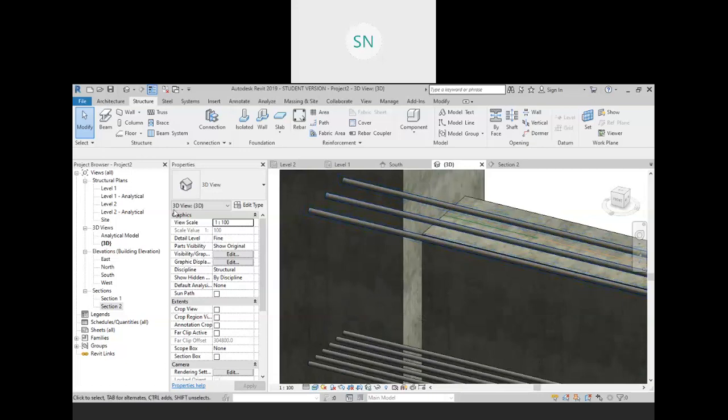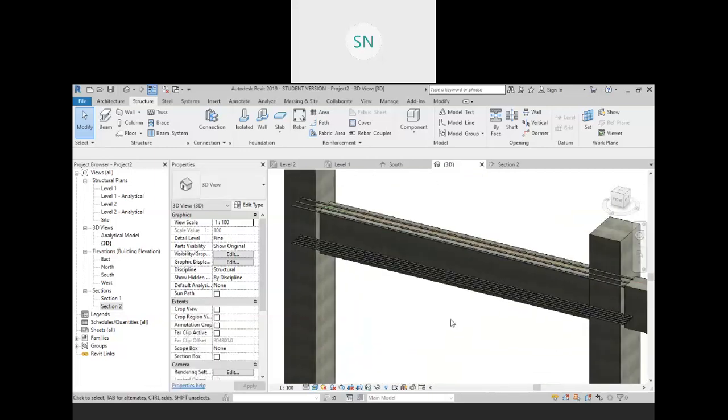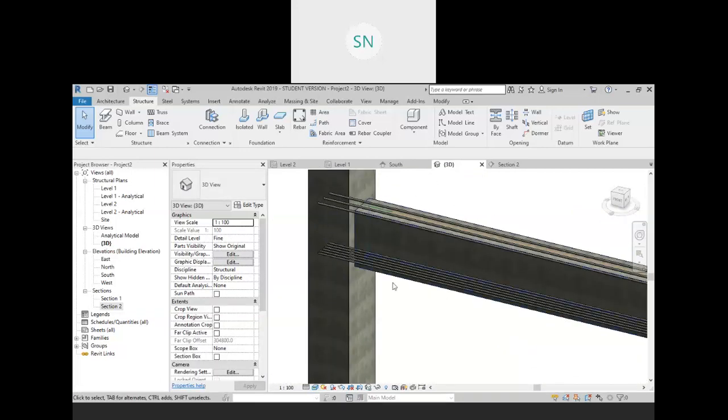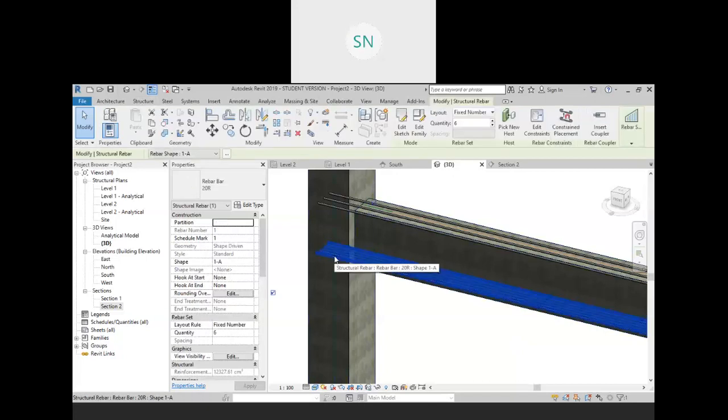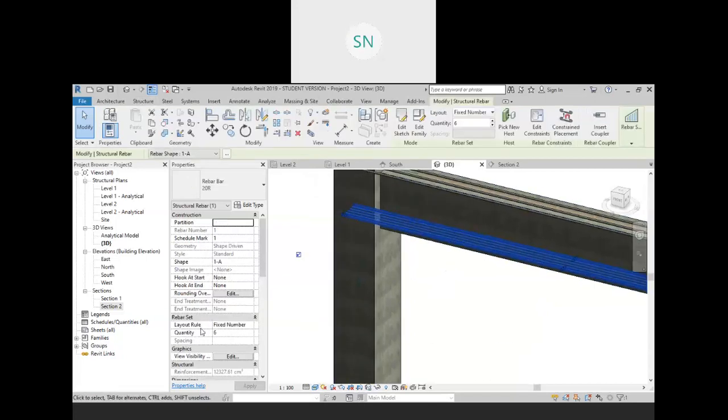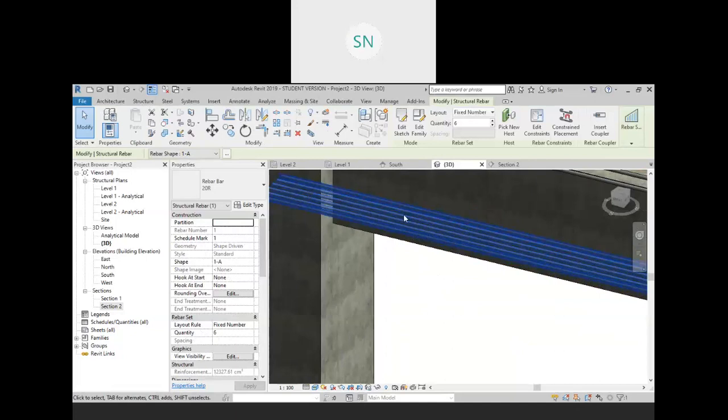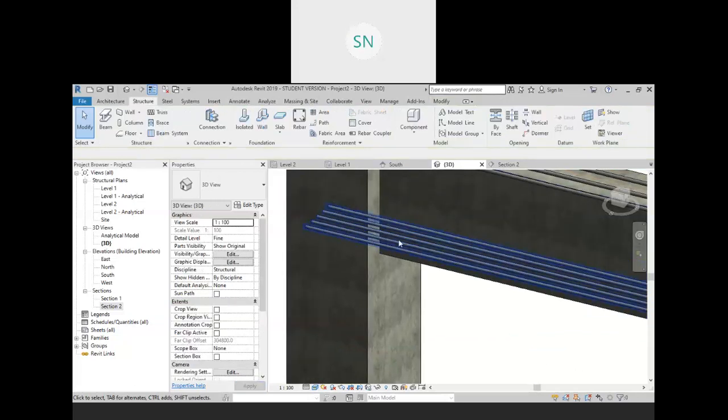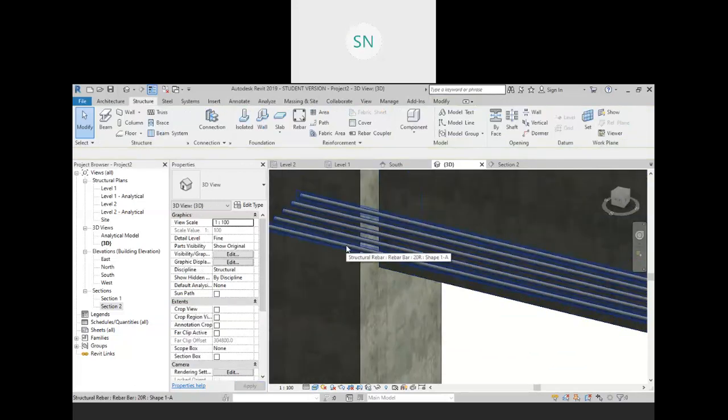So in this way you can actually set your reinforcement, right? So it is clear now up to this point how to apply or how to modify. Now for example, I want to remove some members from here, so you can just select it, and in the group just reduce the quantity, so we can easily update, right?